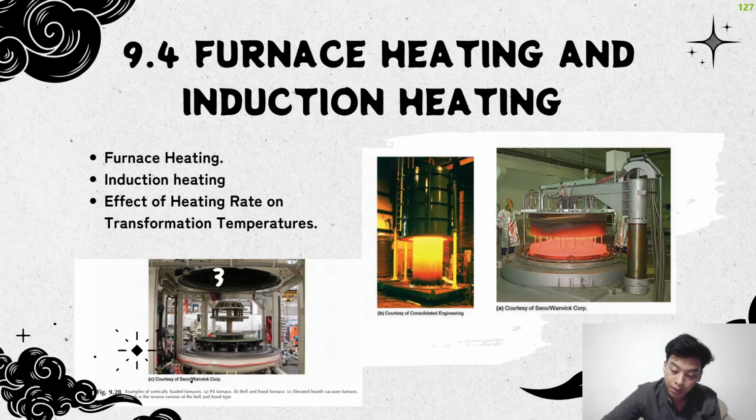Effect of heating rate on austenite formation temperature. When full annealing or full austenitization is required, one important factor, especially with induction heating, is the effect of heating rate on the upper critical temperature for complete austenitization.